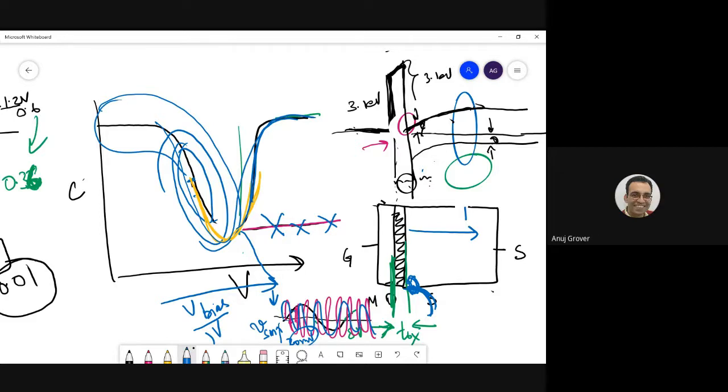I want to make a capacitor of 1 picofarad. If I implement it using a MOS transistor capacitor or a MOS capacitor operated in the accumulation region, I will need an area of, let us say, 10 micron square. Whereas if I implement it using metals, I will use an area of 200 micron square. Why this? Due to dielectric. The dielectric is silicon dioxide in both cases.